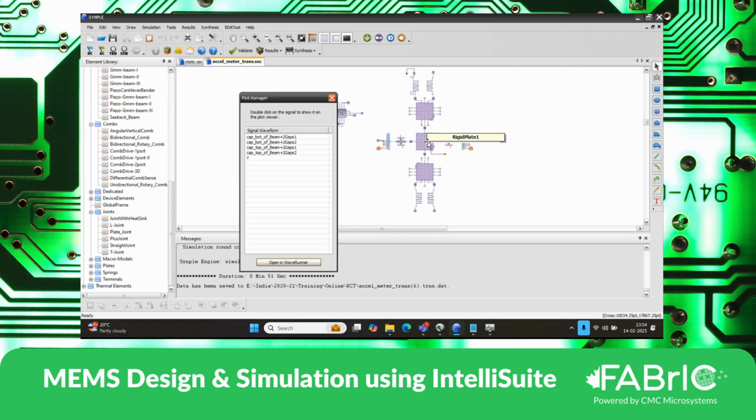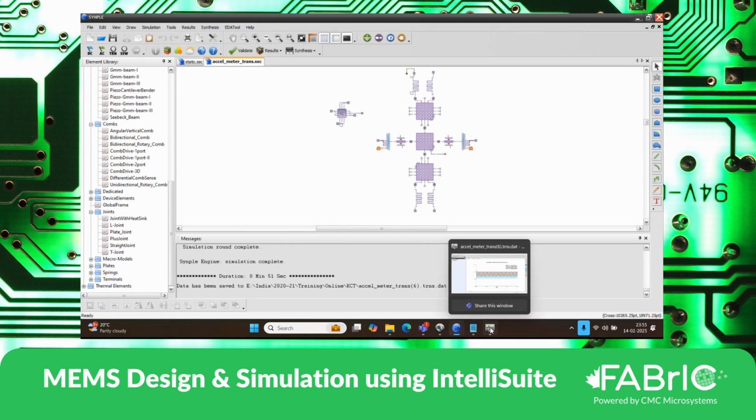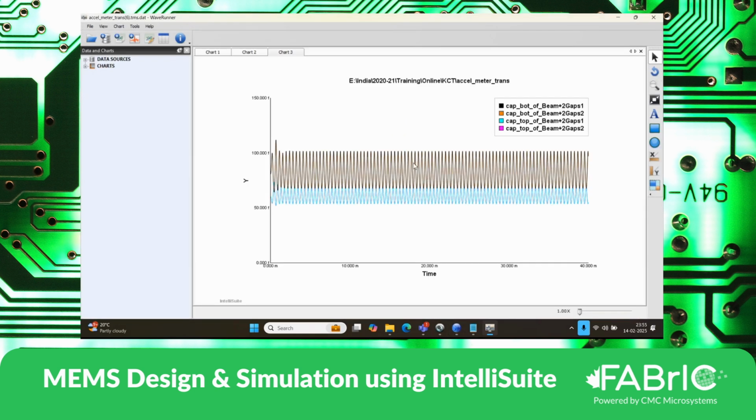Yes, Sripad. I think these are the non-differential capacitances you are measuring even through Wave Runner. Can we do the differential capacitance, like if the comb drives are moving in the y direction? Where the gap is closing, we have more capacitance, and on the other side, where there is a distance between the 2 fingers, the capacitance is less. So if we want to measure the differential capacitance, how can we do that? Yes. For that, what we do here is add up all these signals.